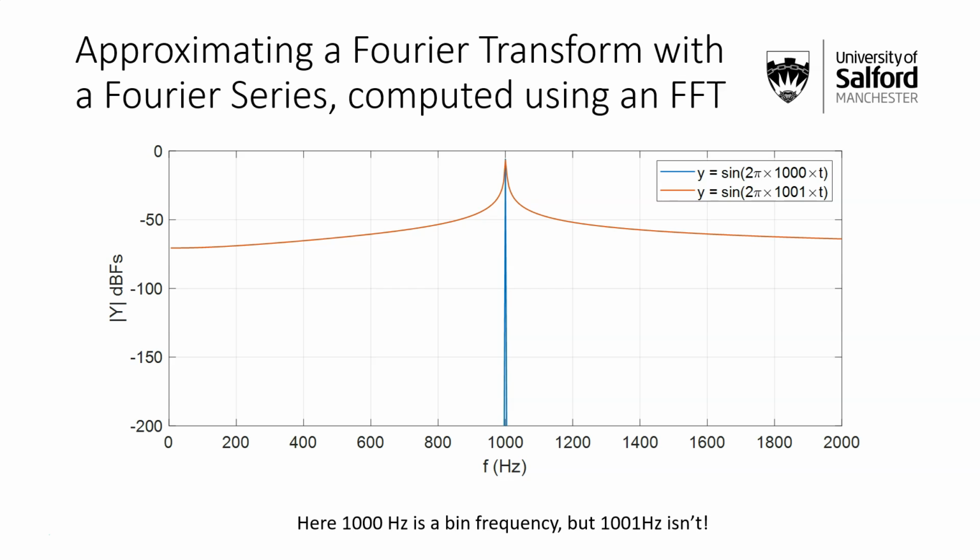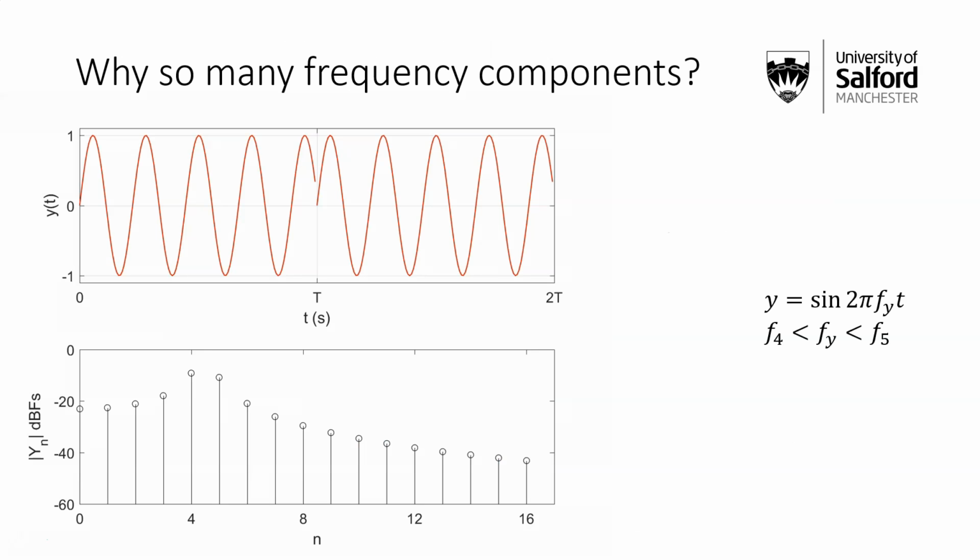So first of all, let's just try and see why that might be happening. If you have a frequency that doesn't quite match the periodicity being assumed, then what you effectively have is one period of the signal come along, 0 to T, and then the Fourier series will just assume that you're starting that again, because it's assuming the signal is periodic. So even though it wasn't periodic, we'll assume it is, and that means we get these funny little things that happen at T, where we might get discontinuities in the signal, jumps, changes in derivative, generally horrible stuff that you can't approximate very easily with smooth functions like sines and cosines.